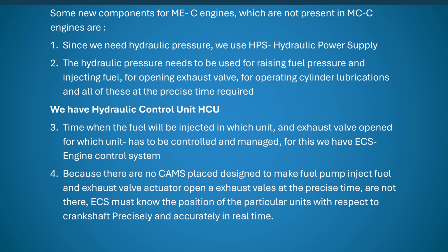Now, since some new components for MEC engines are not present in the MCC engine, these are components which are not there in the MCC engine but are in the MEC engine. Since we need hydraulic pressure, we use a hydraulic power supply. That is something new. Hydraulic pressure needs to be used for raising fuel pressure and injecting fuel, and also for operating the exhaust valve and the cylinder lubricator, and of course all this at the precise time required.